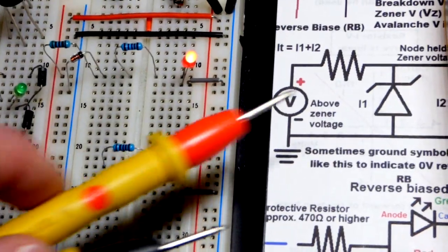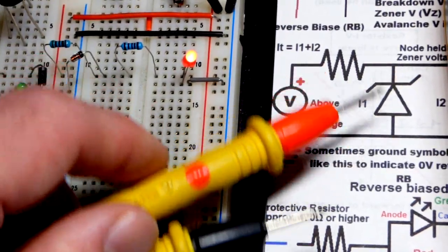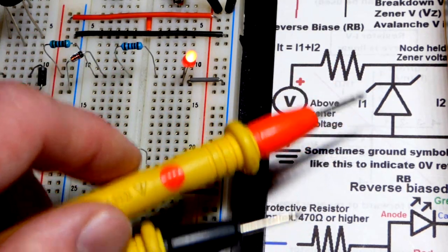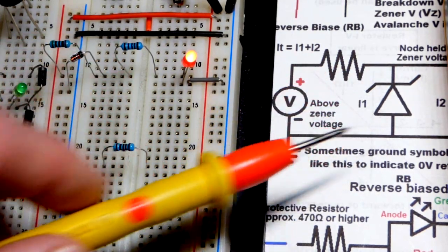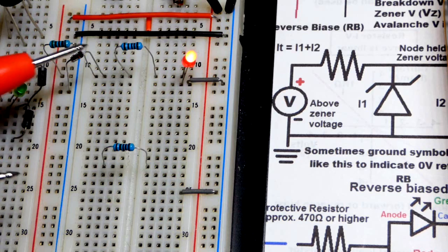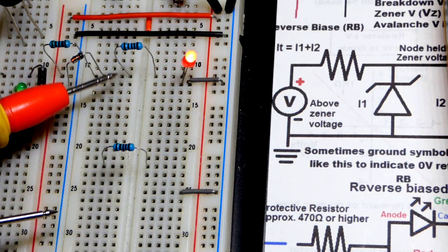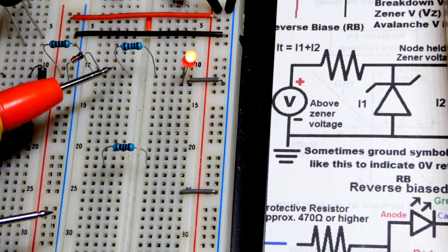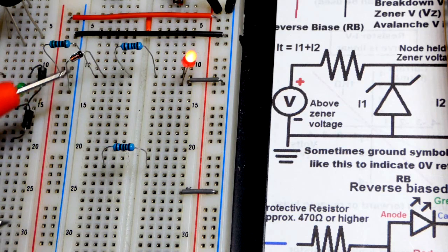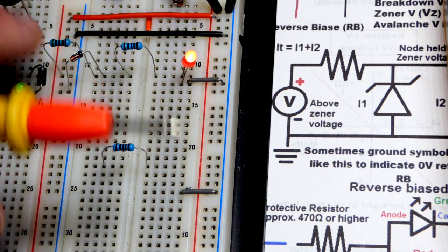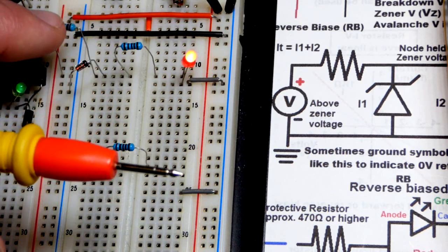We're taking advantage of when you get enough voltage, reverse bias, for it to start conducting. And there's a wide range of values you can choose from. But in any case, it's kind of like a release valve. If the voltage tries to go above 5.1 volts, it passes more current through that diode. So we got positive going over there. So hopefully you can see that right there.